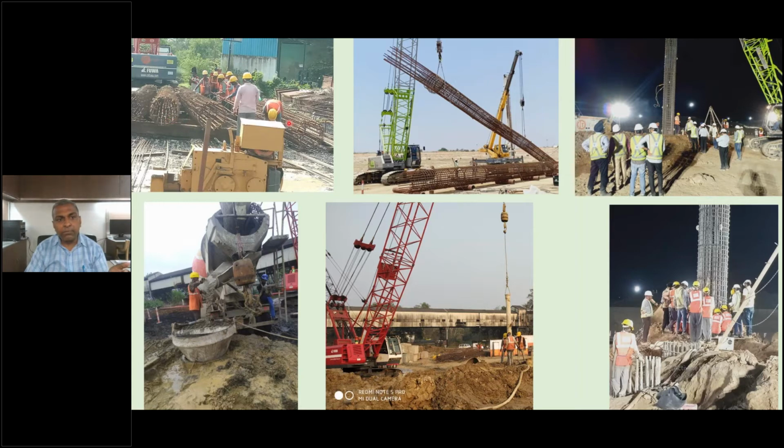So here you can see the reinforcement cage, one of them being lifted up and then inserted inside the borehole, and I would like your attention towards this spacer block, the cover block. These cover blocks are very sharp, round, teethed kind of blocks, as you can see here. These are put because they are essential to make the cover. Otherwise, the reinforcement may be exposed. That is why cover blocks are kept here. This process also shows the lapping of the reinforcement bars, because these are inserted in stages. First one stage is inserted, then the next will be inserted after lapping with the first cage, like that.